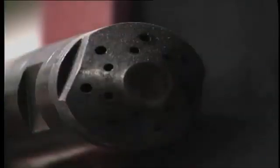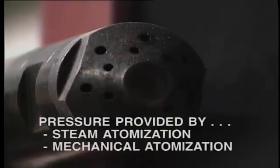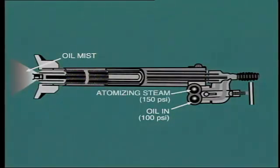Two methods are used to provide the pressure necessary to force the oil through the burner tip. These are known as steam atomization and oil pressure atomization, known as mechanical atomization. In the steam atomizing burner, oil is supplied to the burner at a pressure of about 100 psi. Atomizing steam is fed into the burner barrel at a pressure of about 150 psi, and this serves to force the oil through the holes in the burner tip.